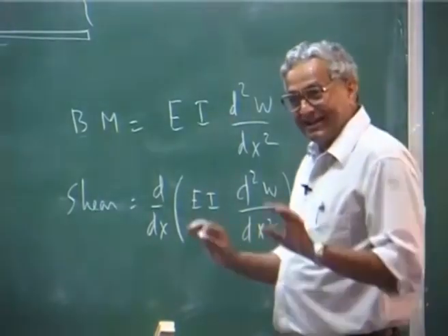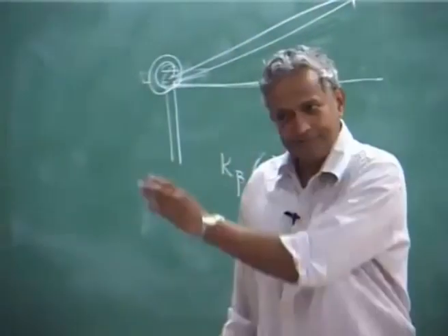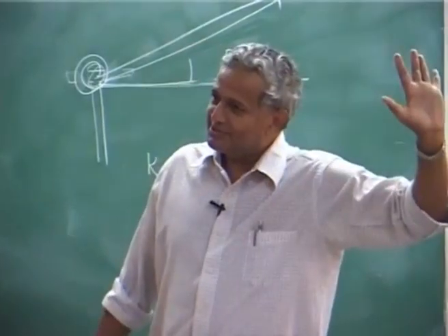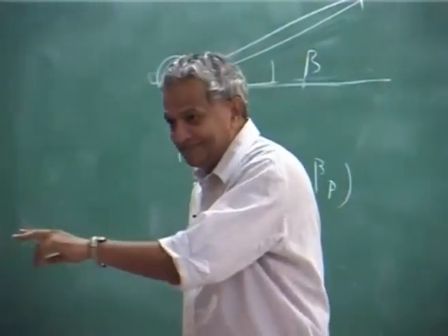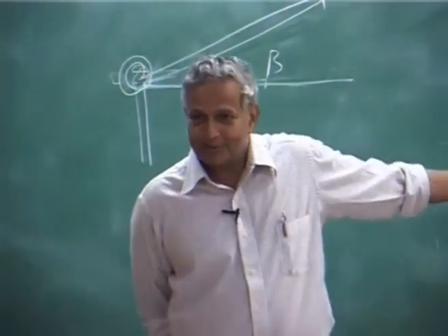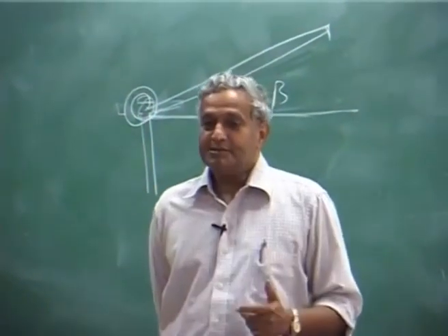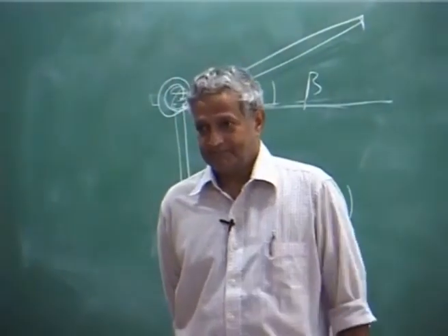One is take the applied load. Please understand. Now, you apply the load, you integrate the load, and you get the bending moment and shear at some section. Another one is you solve for the deformation and then take whatever the standard. In aeroelastic problem, what happens is the load is a function of deformation.